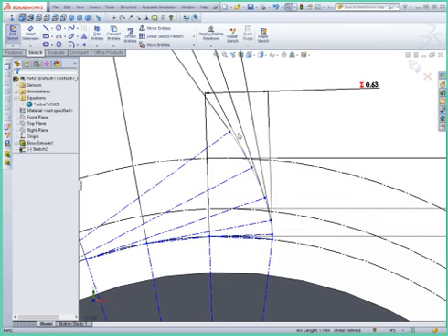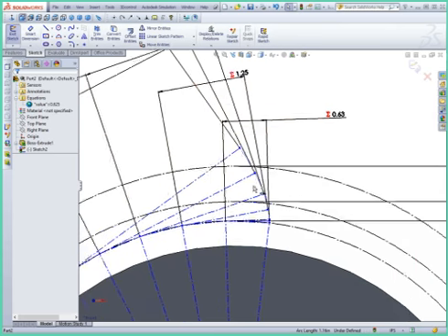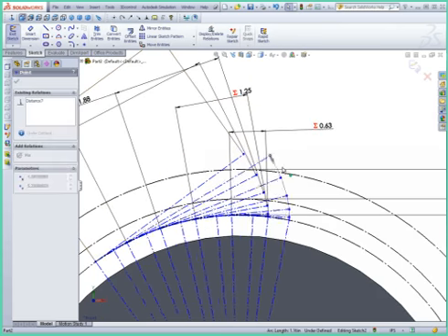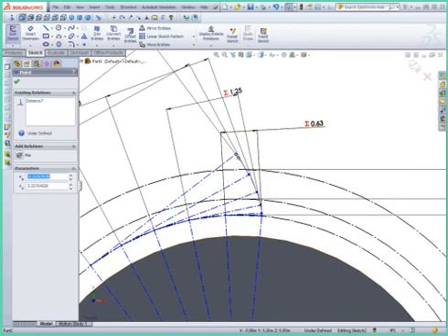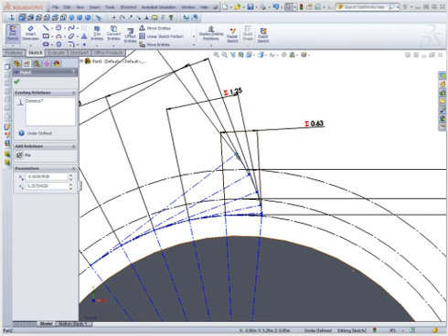So we actually have our 20-degree pressure angle on this tooth, but the last thing is to figure out, well, where does this tooth actually go along the gear itself? And so that's going to involve knowing what the actual tooth width is. The tooth width can be calculated either by the circular pitch or the diametral pitch. And so if you start with the diametral pitch, which is 2, we divide pi by 2 and we get 1.57 inches. Now, that's the actual width of a tooth, but we're going to have 2 teeth meshing together, and so we need to make sure that half the space is allocated to one gear and half the space is allocated to the other. And so we divide that value by 2 again and we get 0.785 for the actual tooth width of an individual gear.